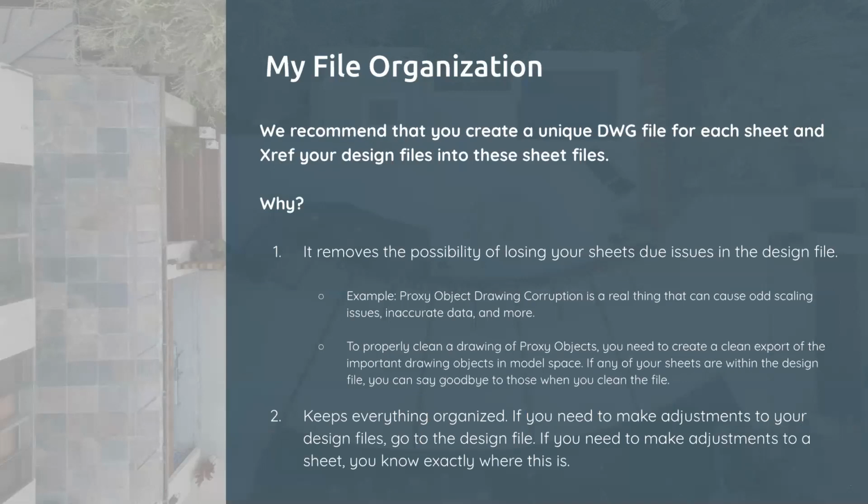You may have read our documentation or heard from one of us that we recommend that you create a unique DWG file for each sheet and xref your design files into these sheet files. And not everybody does this. I know when I was learning CAD, I was more so taught to create several layouts within my design file and set up my sheets that way, which is an option, but we don't recommend it.